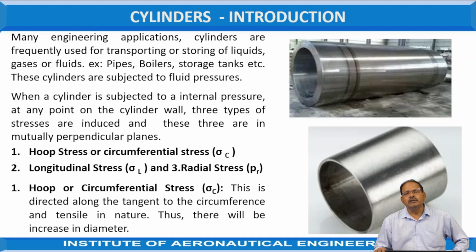When fluids are stored in them, they are subjected to certain fluid pressure, even though it is storage or transporting the fluids. When a cylinder is subjected to internal pressure, at any point on the cylindrical walls, three types of stresses are induced in it. These three are mutually perpendicular to each other, acting on perpendicular planes.